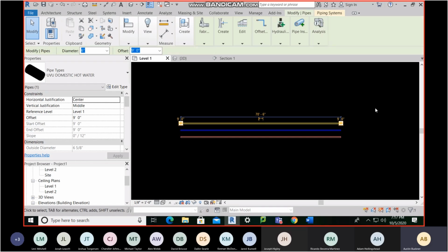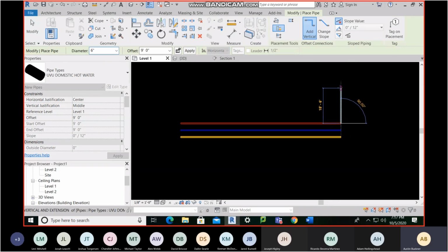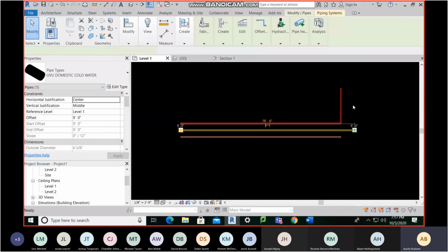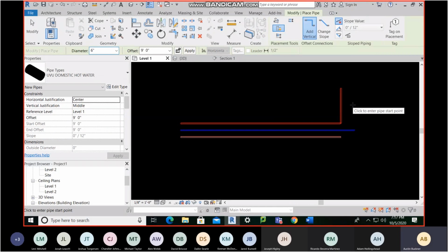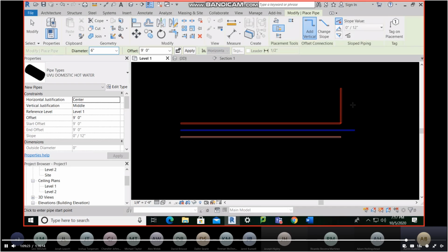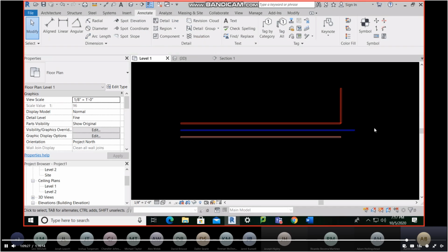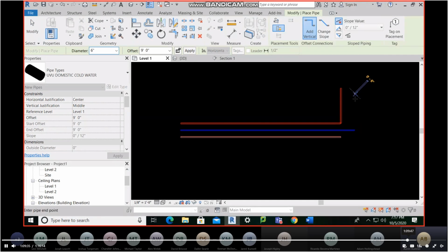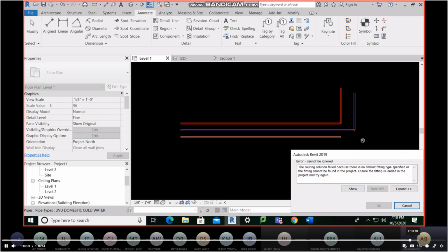Now the hard part. If you notice, I'll come in here and I'll just draw, just for demonstration. Okay, and it should not do it here, but we'll see if it does. It might. Yeah, this is a perfect example. So create our one, and I drew a pipe up and it automatically put an elbow in, put the next piece of pipe up, right? Now, if you notice, and I'll show you that as these commands, so don't worry about these quite yet. We'll get into that next week. But if I come in here to try to bring a pipe up, I'm not going to do this. You haven't told me what I can and can't do here. Okay.